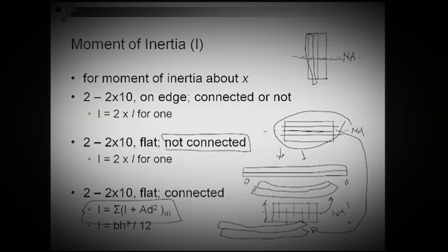I see. Because now what's happening is, Takashi, that's a very good observation, because what's happening for this shape 1, it's on edge. So basically the loads are applied at the top, there is no connection happening on the horizontal, and the depth is not going to increase whether you connected them on the vertical or you did not connect them on the vertical.